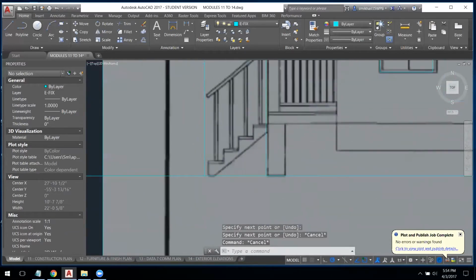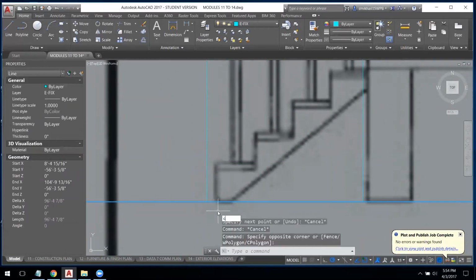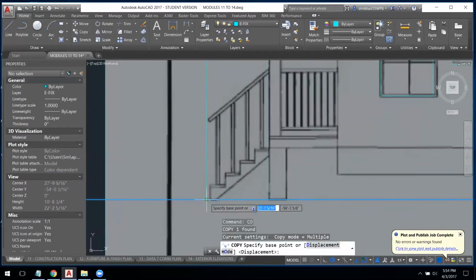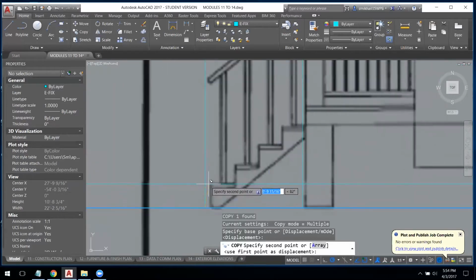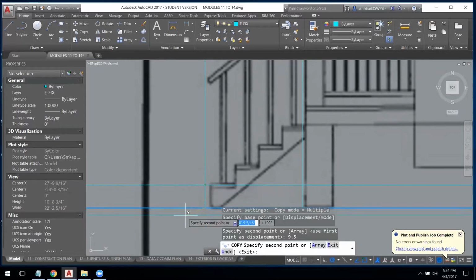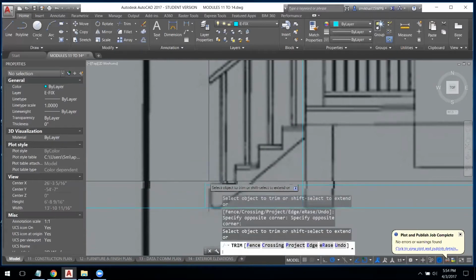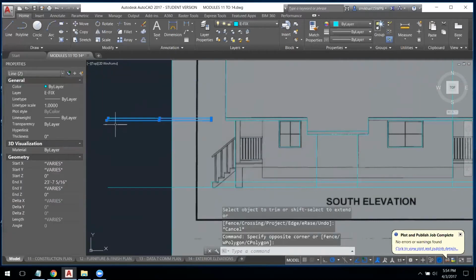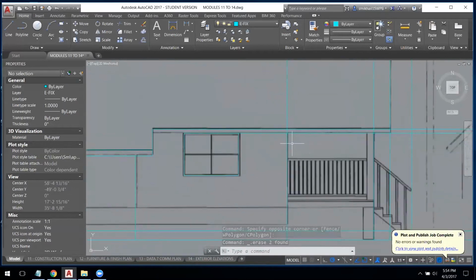In the line of the first step, I'm just going to trim it short by estimating the height, copy, from here to here is about 9 inches to the top, or no, actually more like 10 inches. So let's do 9.5, see how close we get. That looks about right. And here is my first step drawing. And I can get rid of all the extra additional lines that are distracting me in my model.